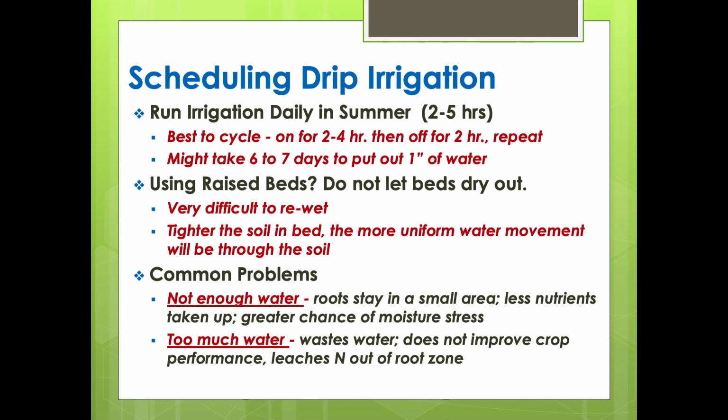So it takes time to keep that water out there, and that's why you never want to let your beds dry out completely, because if they do, that drip, drip, drip takes an awful lot of time to re-wet a bed that's been dried. So anyway, does everybody understand that? I think that's probably the most important take-home message you can get. Never just let it run for 10, 12 hours.